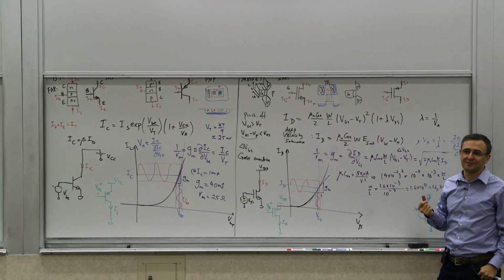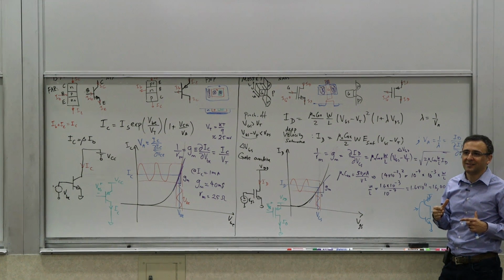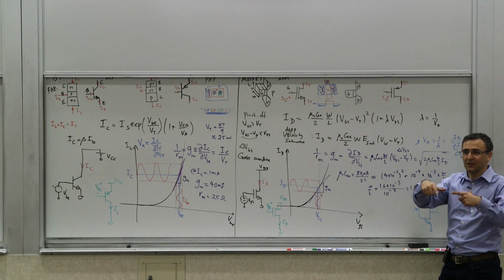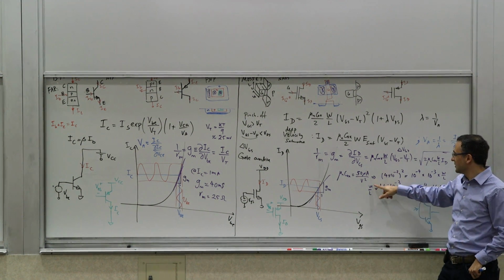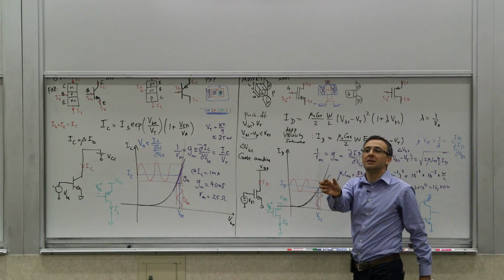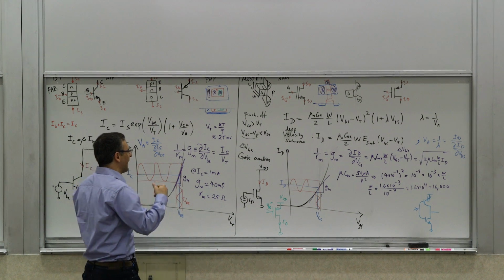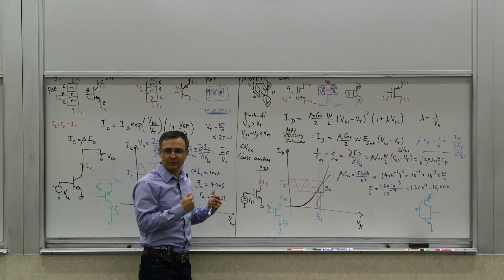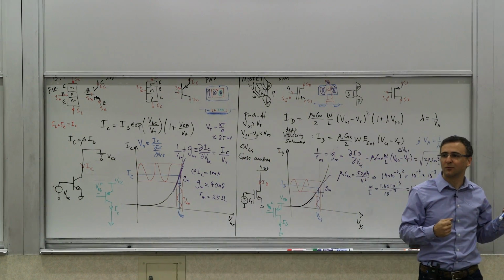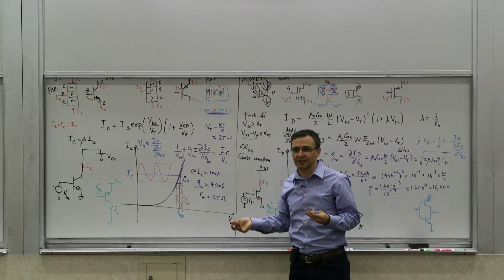What was the capacitance, roughly, if you think about the gate capacitance? What was the expression for it? The area of the gate would determine the capacitance. So the area is W times L. And your L can be at a minimum, so the capacitance can be larger. So again, intrinsically, the frequency behavior of these guys is better than these guys. Because for the same transconductance, you will have more capacitance. Or for the same capacitance, you will have less transconductance.